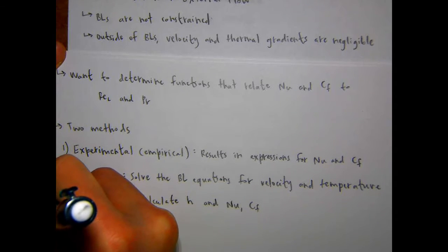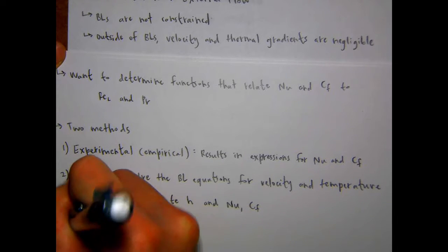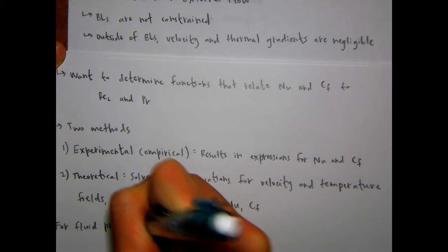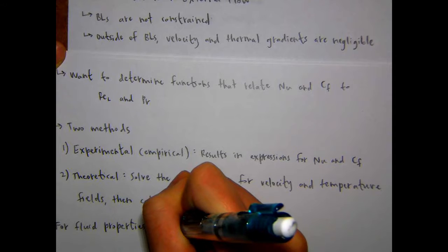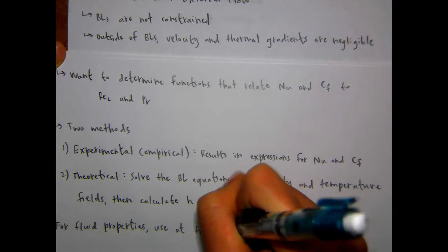And as we said before, we'll talk about solutions for a lot of different geometries, so it's important to know the assumptions and geometries match up with the equation that you're using. And we're going to have to look up fluid properties pretty frequently. You need to know the viscosity, the density, the Prandtl number. As I mentioned, I think on Wednesday, the fluid properties do vary with temperature, and we're going to evaluate them at this film temperature.